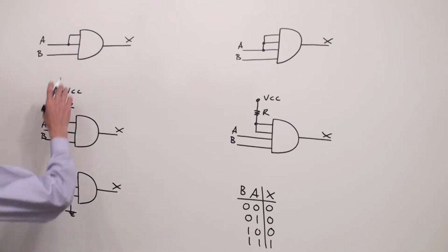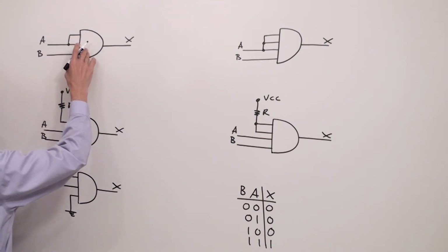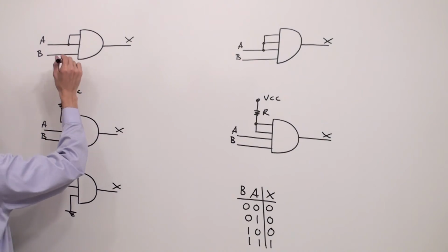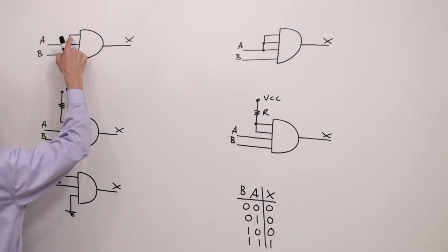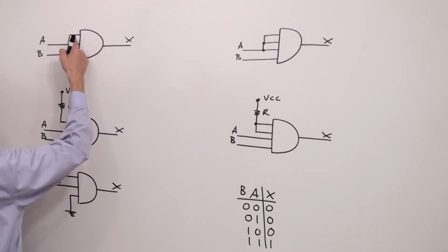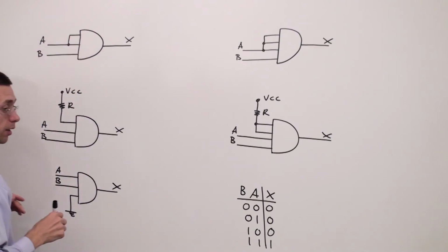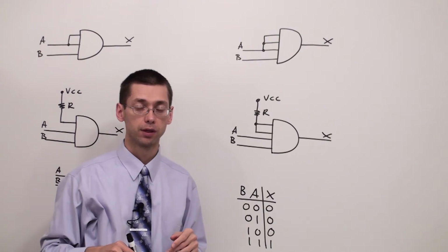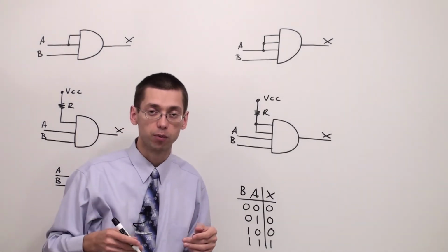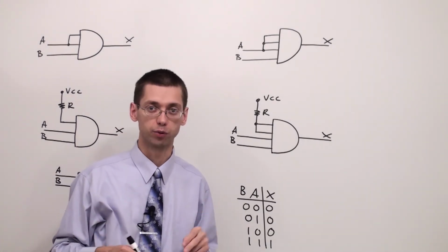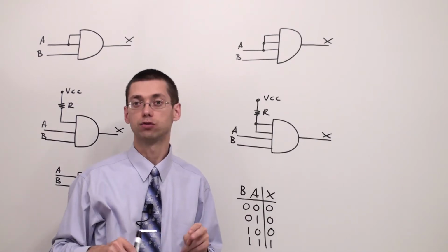First gate, we have a 3-input AND gate. As we said, we cannot leave one of the inputs or many inputs open, but in this case we have just one extra input. Why do we make this connection? Because sometimes at a particular moment you do not have a 2-input AND gate, but you have a 3-input AND gate.